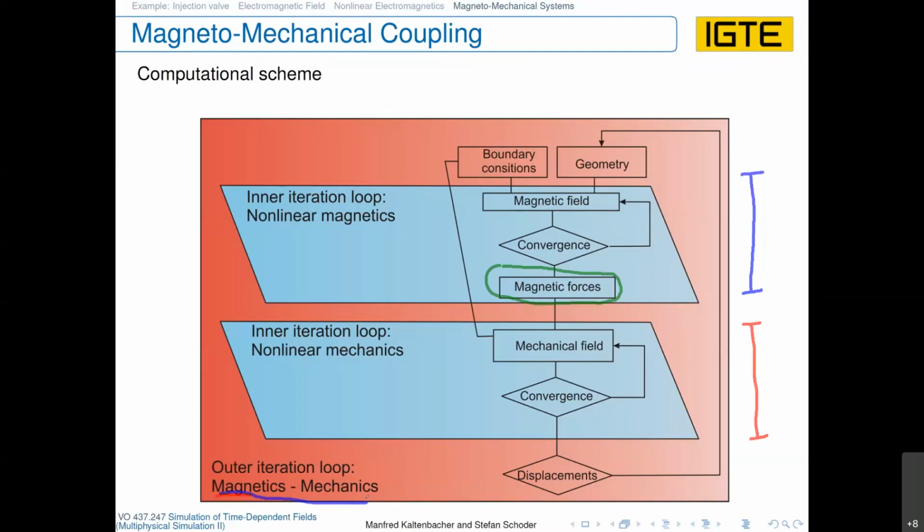Regarding the mechanical forces, no, we not only have the Lorentz force. As we have seen before, in quite most actuators, as well as electrical machines, you clearly have an iron core in order to guide the magnetic field, and then at the interface between the iron core and the air, you have these pole forces, these surface forces. And within the volume, when there are also additional currents, that could be the currents in coils or eddy currents, you have these additional Lorentz forces.